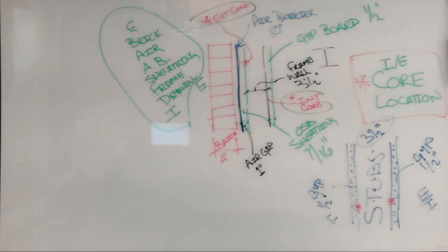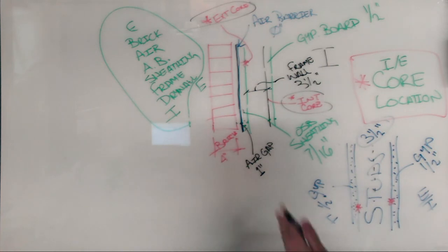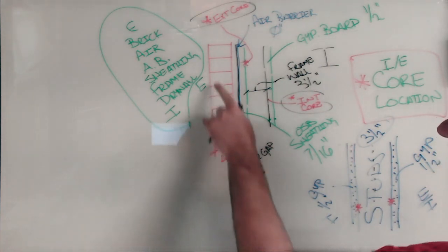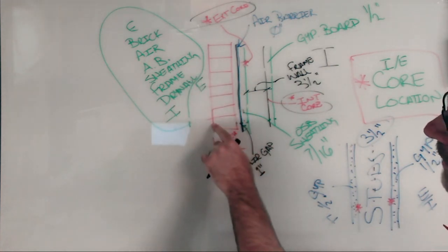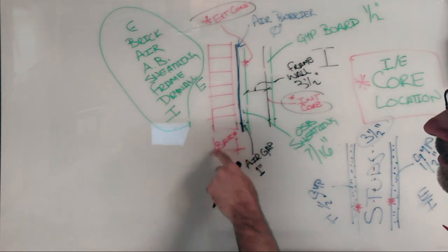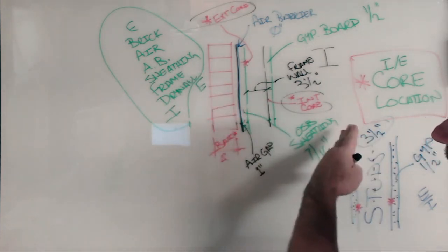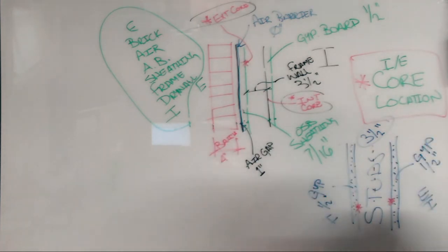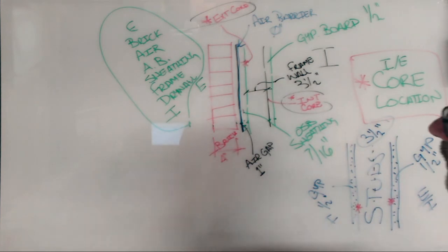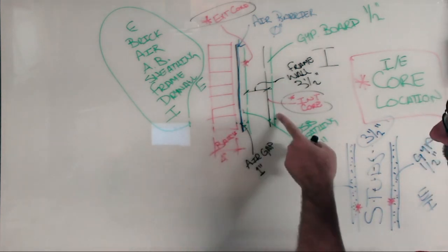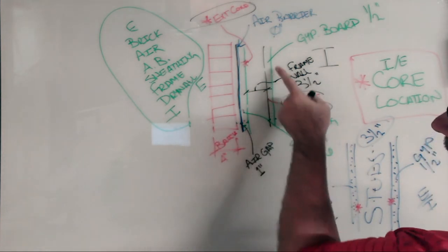The next one that we have is finished face exterior. Revit goes, what's the outmost thing to the exterior? Oh, it's the edge of the brick. That's what we're going to use as our line. That's what we're going to draw from. Ignore everything to the inside. Everything just comes inside. Quite the opposite, we have finished face interior. In this example, it would use the drywall, and that will be the line that you would draw.